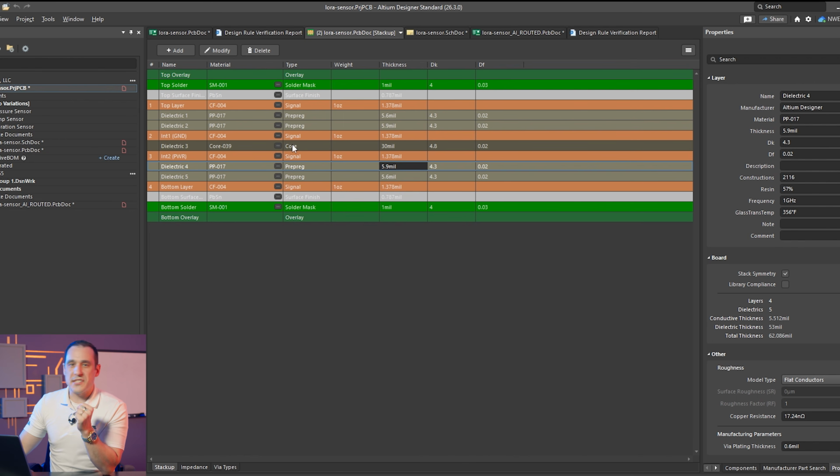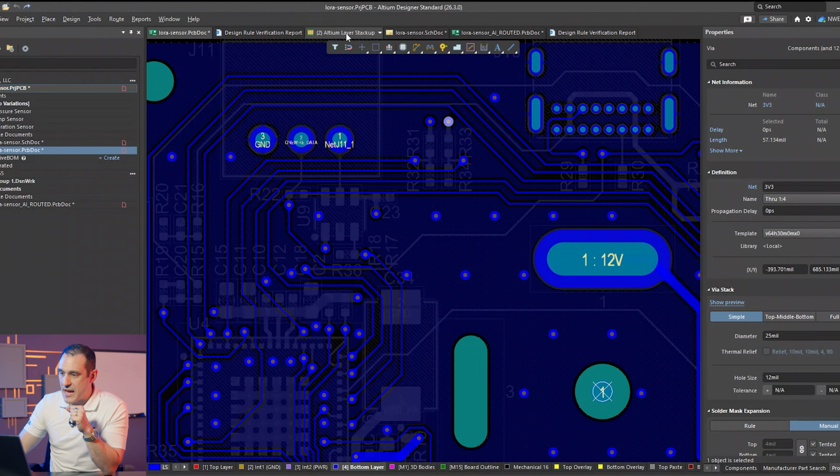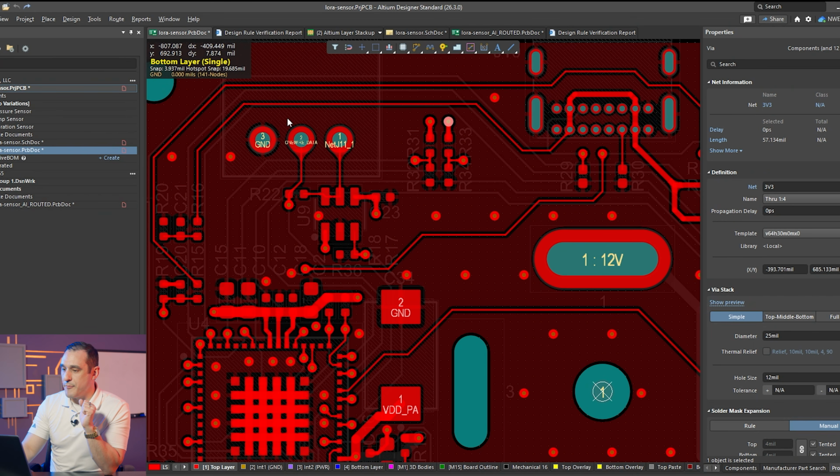And that's one reason that we might want to include that copper pour on the bottom side. This is something that I discussed recently with Dr. Todd Hubing on an episode of the Altium podcast. So having that ground pour helps to provide that ground reference for these signals on the bottom side, whereas the signals on the top side have both the copper pour that's balanced on the top side and then the ground layer on layer 2.